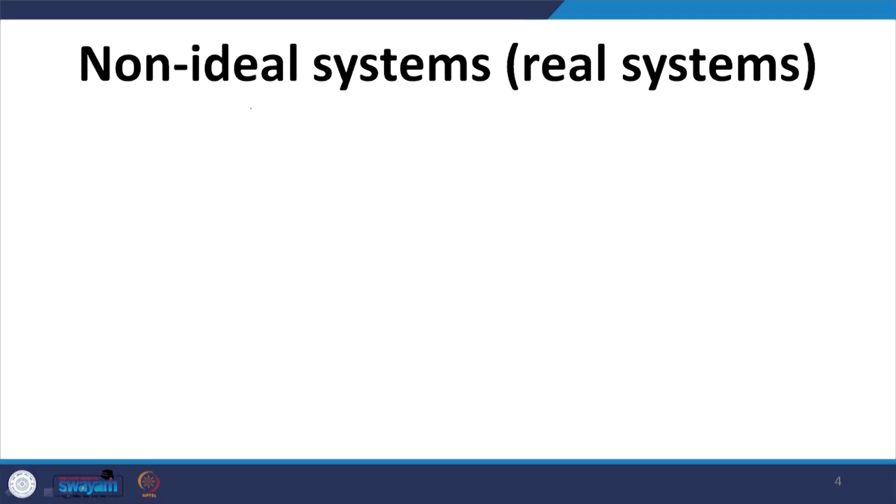When we are talking about CSTR and plug flow reactor, we always referred to them as ideal systems, right. As in, we are assuming complete mixing within our particular CSTR. And let us say if I want to understand how a lake behaves, we typically apply the CSTR model to the lake. But in a lake, let us say the inlet is at one end and the outlet is at the other end. Do we really presume, or can we presume, that the lake is completely mixed? No, right. That is not how it works out there, but these are the assumptions we are making.